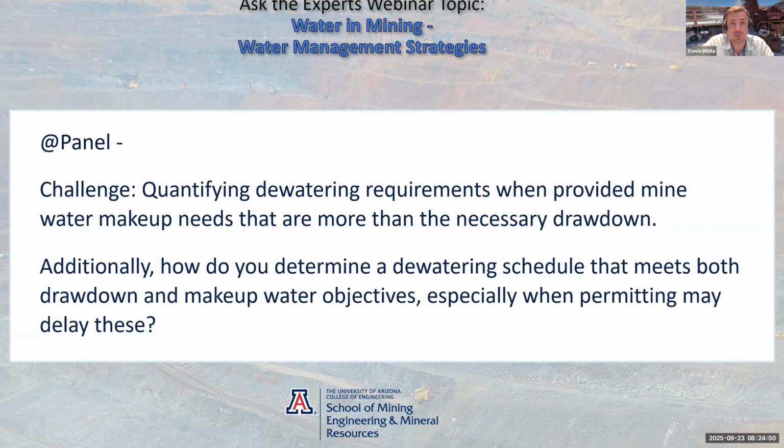So make sure you've got sufficient storage, like Simon said. Make sure that your pipeline and your reticulation and all your infrastructure has got enough redundancy that if you do fall behind, or you do need to bring in more water, whatever the case is, that you're able to do that. That's from pumps to pipes to dams. And then make sure that your permitting is done in advance, and there's enough flexibility in that permit. So never apply for exactly what you need. Always work in a bit of contingency or a bit of fat in that permit.